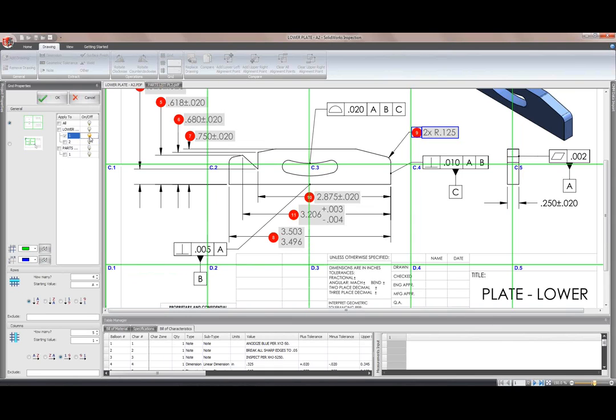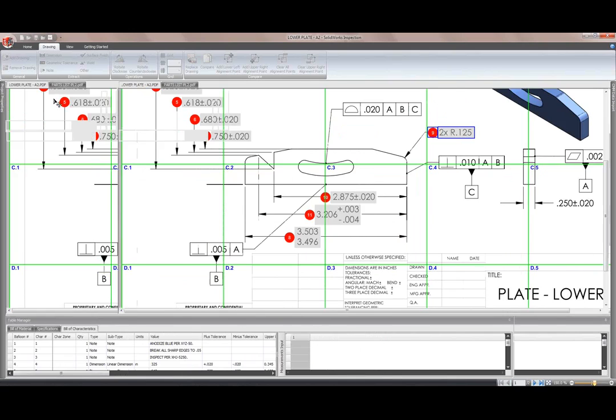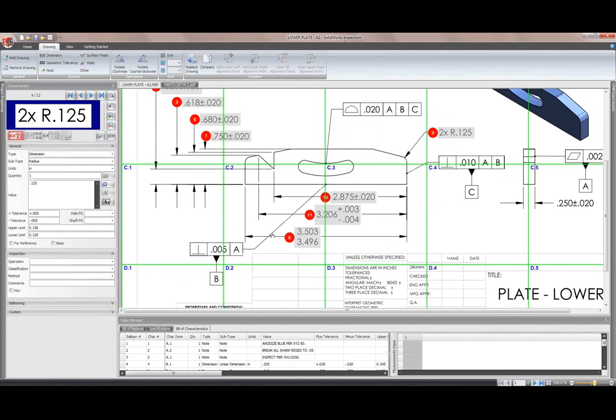There's just a hide show toggle on the side here, and we can apply that to all drawings or just a single drawing. So the little tick box here just applies it to a single drawing. Or maybe you only want to apply it to an area of a drawing, so there's an option for that as well if you just want to do that. We can change the colours of the grid references and grid lines and things. But if we just OK that, each item that's been